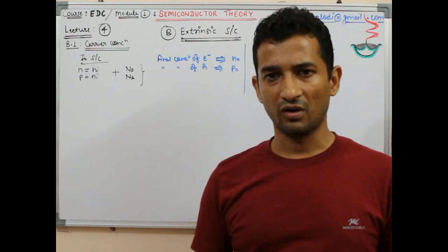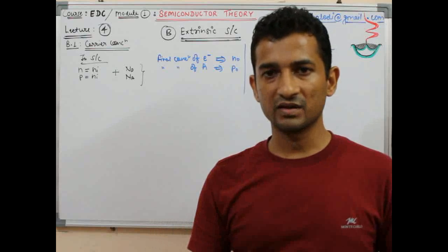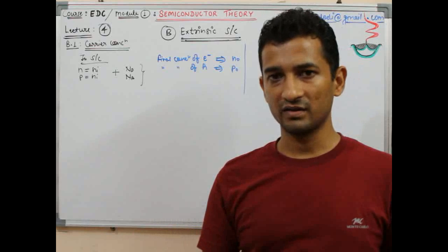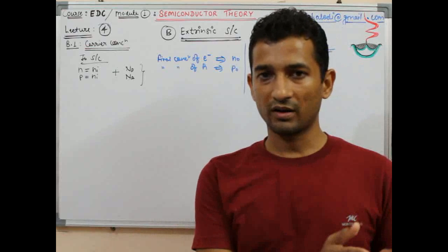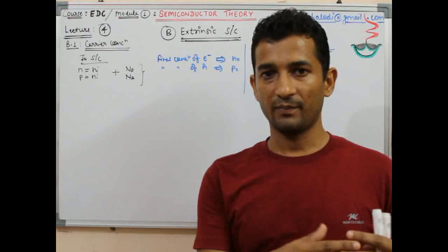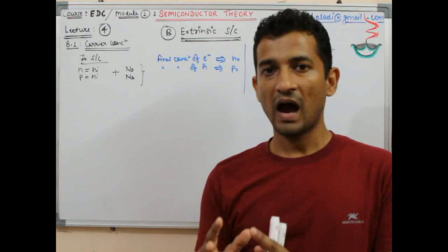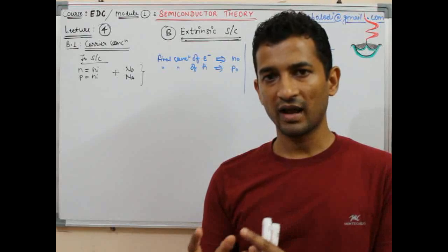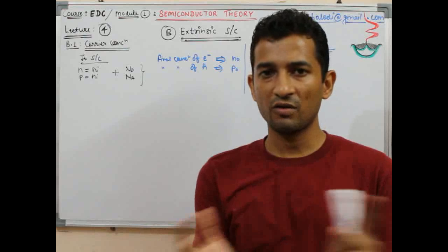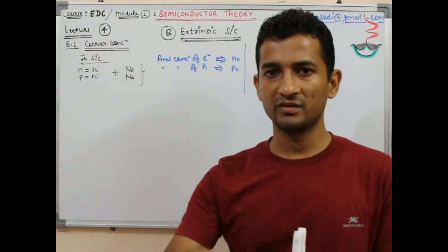Then it remains neutral, because whatever atom has come inside was neutral actually. The impurity atom, once it enters inside the silicon, donates one electron. So we assume that one electron has been donated, so there should be an excess of negative charge, but that one electron is equally balanced by the ion left behind. It has got detached from an atom which has now become a positive ion. So a positive ion and one electron make a neutral entity, and therefore all the external impurity insertion was neutral.